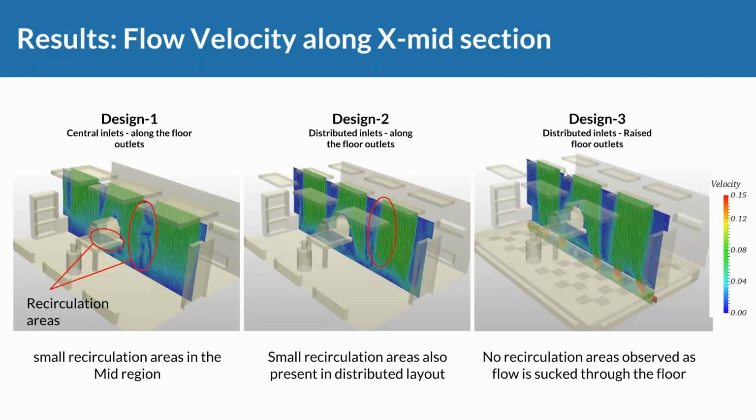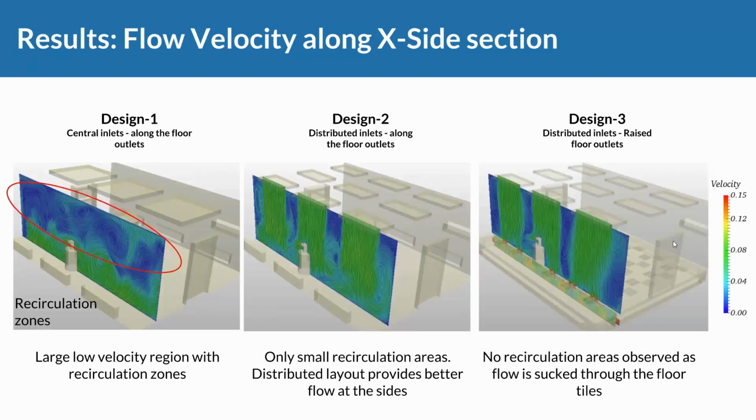Same story now with another cut section perpendicular to the first ones. We can again identify recirculation areas in different regions, and one more exactly where the contaminant enters. Here we can really interpret something, because we can see that we've got an effective removal of air, an air exchange happening here. This looks good. But if a particle enters this region, it could stay around here, and that's what we do not want. So contaminant removal would not be effective at that point.